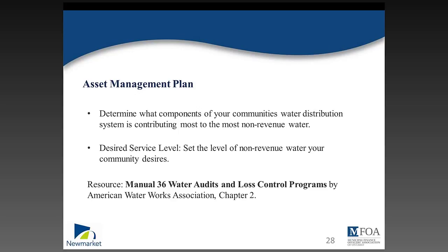I have read stories where intuition has failed water distribution utilities in the past, where great financial resources were invested in order to address one water loss issue with little results. That's why I encourage you to meter and estimate all the sources of non-revenue water feasible. Then set a target for where you would like to be.